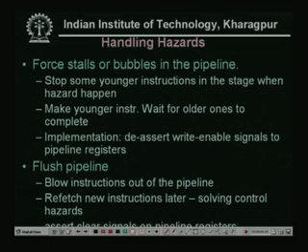Again, stalling means that it will wait for some time until the first one completes its use. Then in that way we can handle the hazard. And deassert write enable signals to pipeline registers. This is called the implementation, that is, how handling hazards is implemented, using write enable signals to pipeline registers.